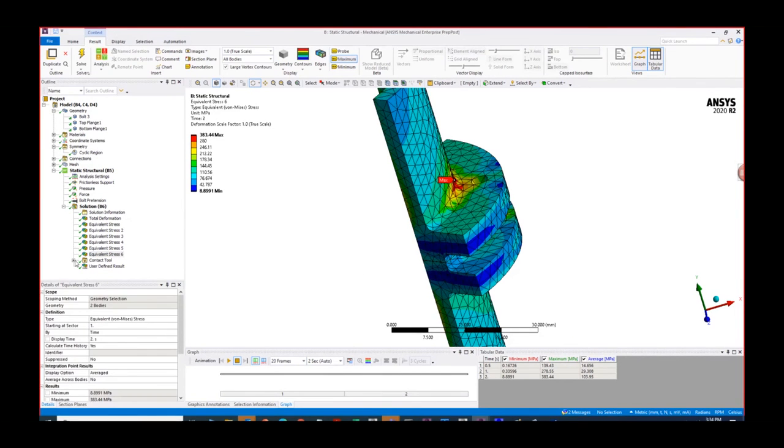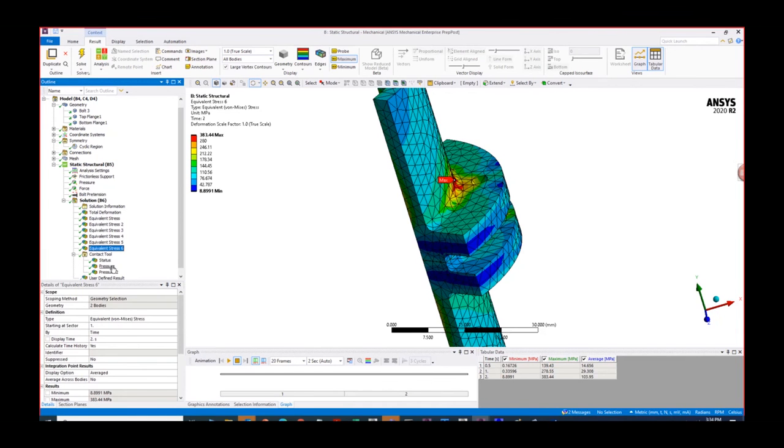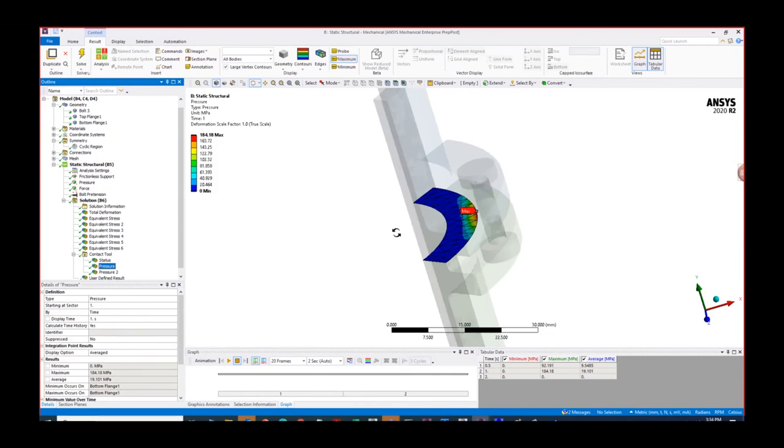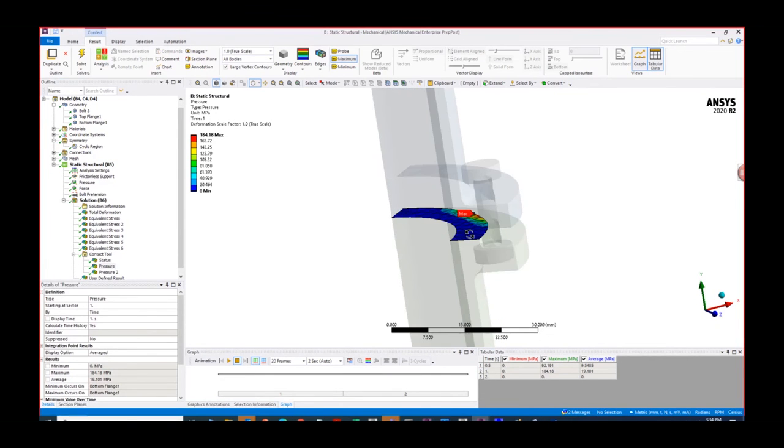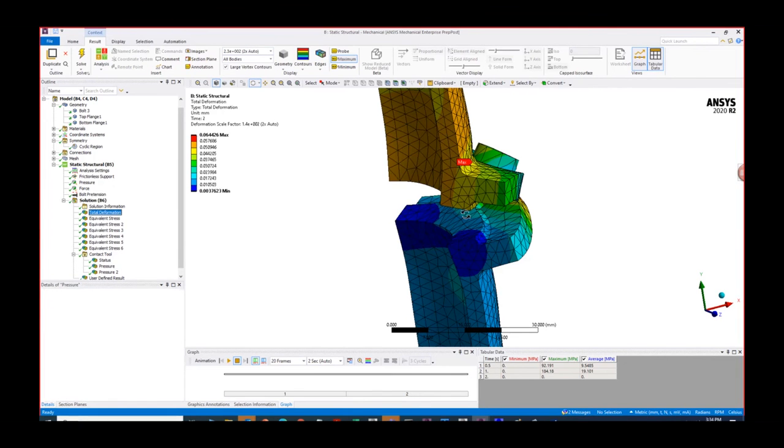And this problem is not very practical as such. For example, if you look at this, the bolt configuration is not good enough to completely keep the joint in a closed state. As you can see, the bolt joint will open up.